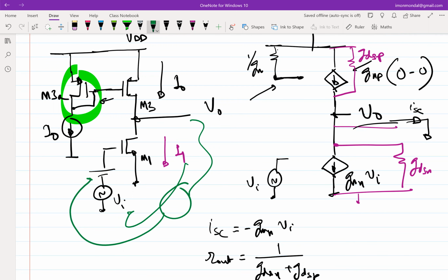We assumed while designing this open loop amplifier that there is a certain bias. After you put it in negative feedback, sometimes you will see that the bias goes for a toss. In that case, you will think that whatever was taught in class is wrong. But that's not the case. It's basically because the bias goes off, and if bias goes off, your small signal parameters go off and you have a problem.